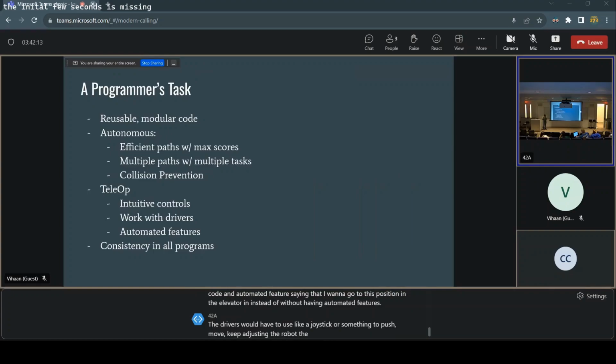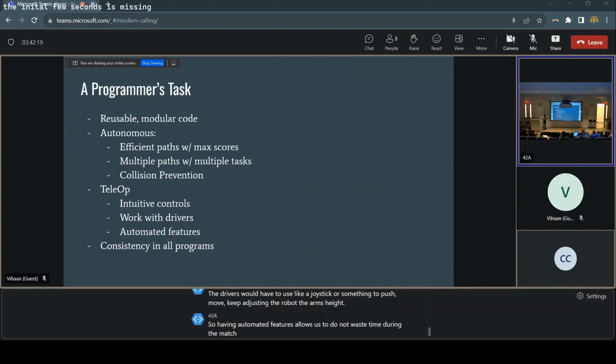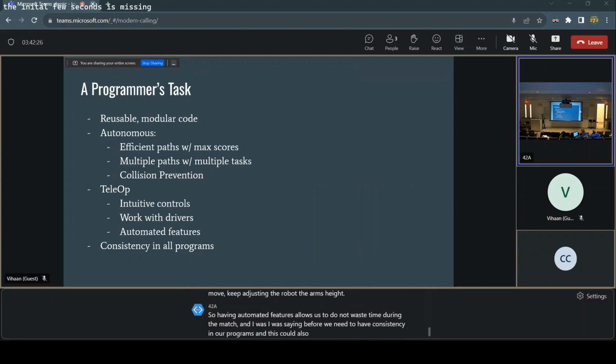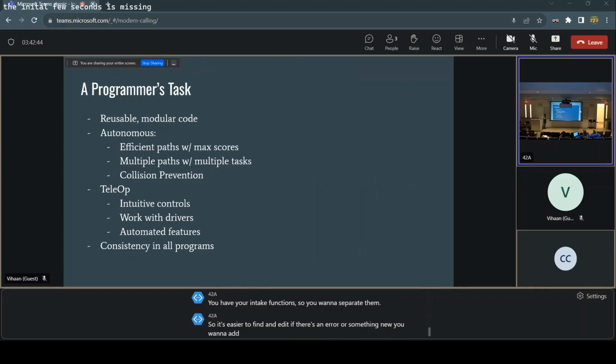So during autonomous, we want to move the robot around, obviously, to score points. But to do this, there are two basic ways of doing it: time and encoders. Time would say that I set all of the motor powers to 0.5, half speed, and we're going to move forward for 5 seconds, so add a sleep for 5 seconds, and then stop the robot, setting the power of the motors to 0, no power.